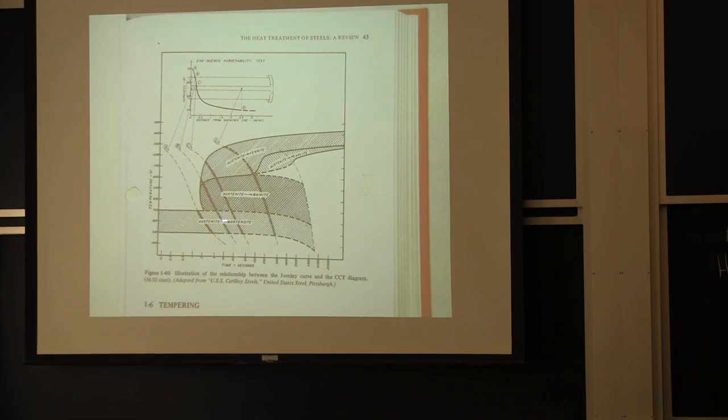It turns out the austenite to martensite is a somewhat unusual type of transformation. It doesn't just occur in iron carbon alloys, it occurs in nickel titanium alloys, some copper based systems, a number of different systems have martensitic phase transformations. The martensitic phase transformation is basically just a shearing or displacement of the crystal lattice. So it goes from one structure to another. And that means it occurs at something close to the speed of sound.